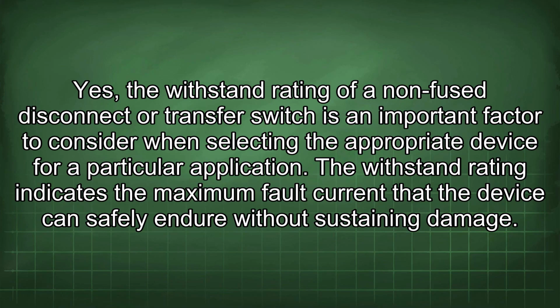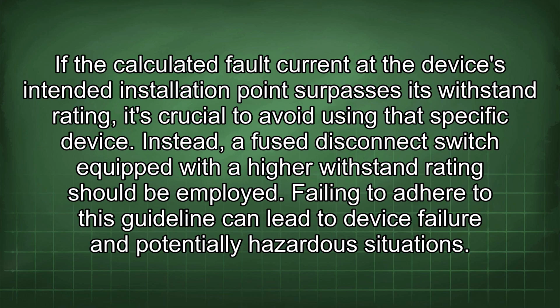Yes, the withstand rating of a non-fuse disconnect or transfer switch is an important factor to consider when selecting the appropriate device for a particular application. The withstand rating indicates the maximum fault current that the device can safely endure without sustaining damage. If the calculated fault current at the device's intended installation point surpasses its withstand rating, it's crucial to avoid using that specific device. Instead, a fuse disconnect switch equipped with a higher withstand rating should be employed.